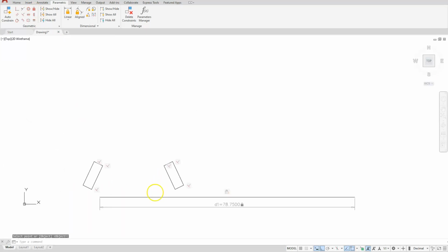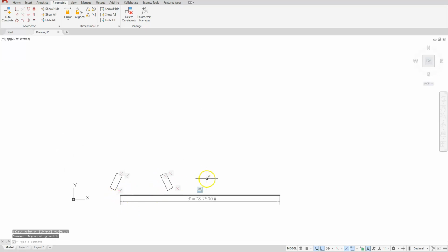So now what I just told AutoCAD to do was make sure that that endpoint doesn't move. If I select on this line just with the grips, and I move this one, you'll see that I'm able to move that line up and down, but that end will not go anywhere. Even if I hit the enter button to try to move it, that will stay still.